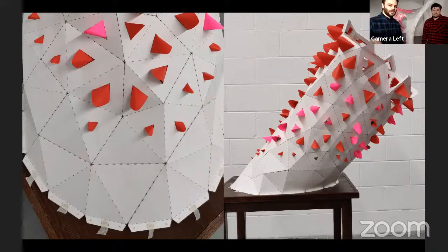And you see there's different sized petals. And each of those is just friction fit right into the paper. And at this scale, testing this material assembly one-to-one, we learned a lot. First of all, the diameter of our surface here was a little too large, and also the base. You can notice we had to tape the tabs onto the table. The base needed a rigid frame to attach to, so we designed a plywood anchoring system right at that flat planar edge.